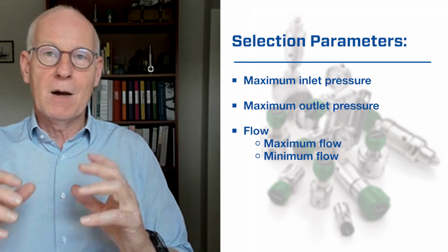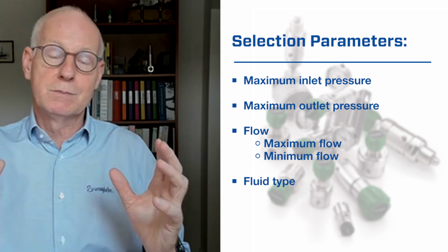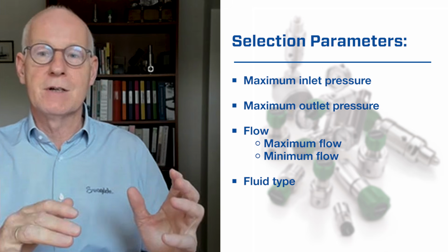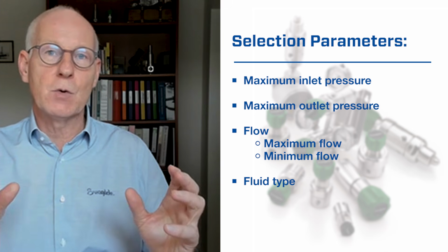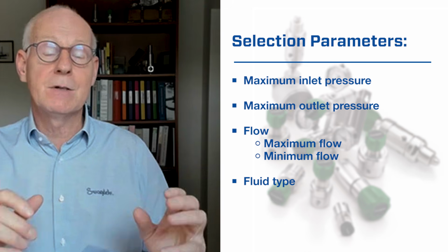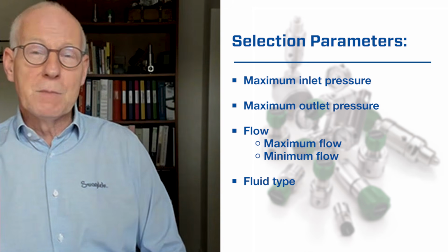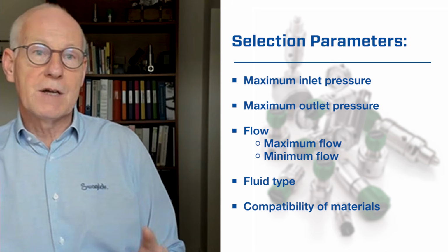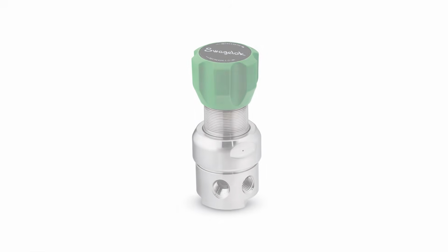You also have to think about what is the fluid I want to reduce in pressure. Is it hydrogen, or is it CNG, so compressed natural gas, or is it simple nitrogen? So it's also important to realize the compatibility of the materials. He has to select the correct materials to select the correct regulator.